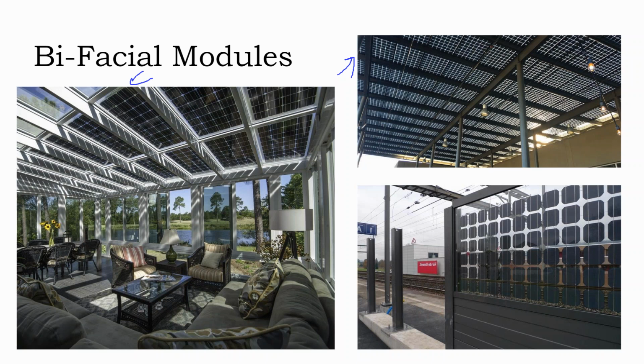If you are going to capture light on the underside of it, it needs to be up in the air, not right on the roof line. And furthermore, shaded light conditions, PVWatts will tell us that on a very shaded day, you're only going to be producing 10% of what you would be doing on a sunny day. And so you can only pick up 10% more light. And if the solar array is only 20% efficient, that's a 2% increase in production.